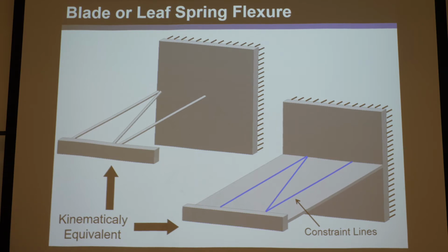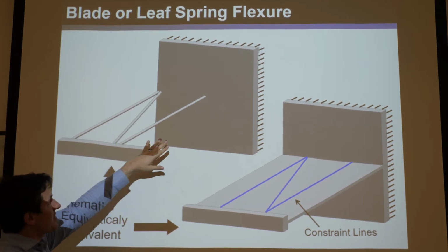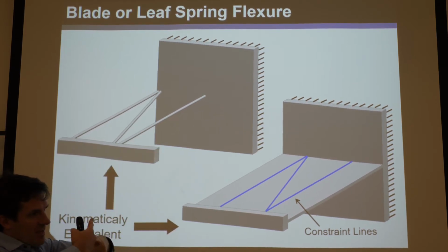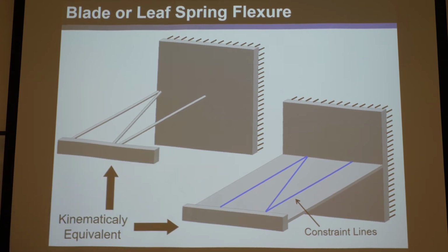Okay, but the truth is, once they have some finite thickness, you can fit more blue lines in their geometry and connect these 2 rigid bodies, and they can be kind of off angle. They don't have to be in the axis perfectly, and it starts constraining unwanted directions that over-constrain things a bit.